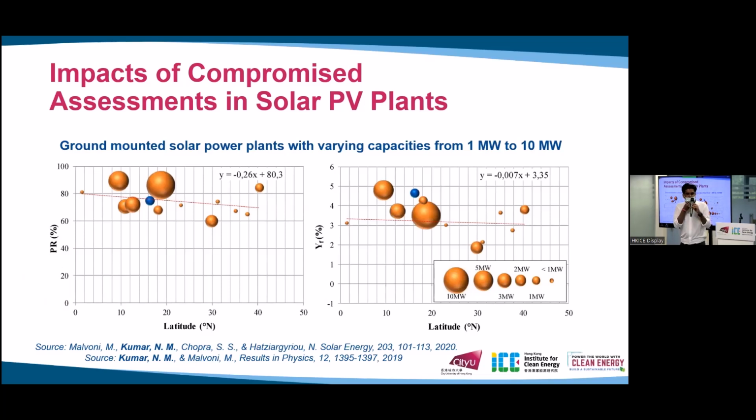This performance ratio accounts for all the factors that interfere in the lifetime of a plant. Let's say a solar power plant is installed; it will be there for at least 20 to 25 years, and if it is organic solar cells, maybe less than 20 years. Accounting all factors, we estimate this PR as 1. A nominal PR would be somewhere around 80 to 90, but we have seen most plants falling under 80. The reason is maybe they were not planned effectively, or the infrastructure was not planned in the way it should be. The same happened with the yield factor.